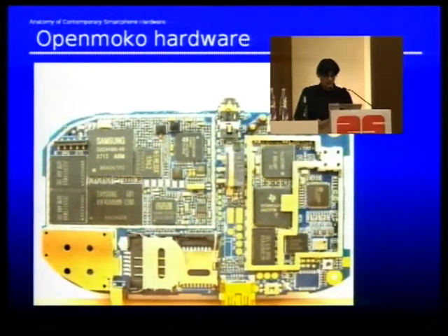And the section which has the frame for the shielding cover over here is the actual GSM modem side. This one is the baseband processor, then we have the DSP over here, some flash and RAM in one package down there, and this is the RFPA, I think, over here, basically.